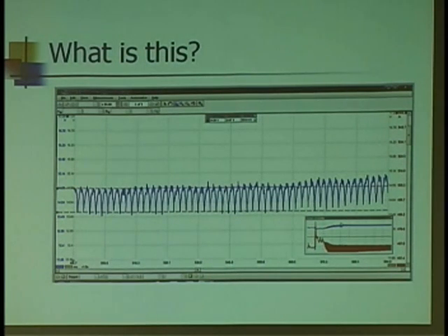Got weird drivability problems going on? Check your AC voltage. If you get anything more than what Pierre was sharing on some of these newer cars, even as much as 200 millivolts, that is too much. Computers like yes, no, ones and zeros. When you start adding an AC component, aren't I giving a whole bunch of yes, no, yes, no, yes, no, yes, no? And the computer's going like, what the hell are you talking about?